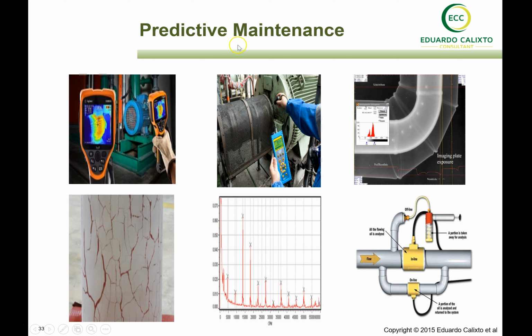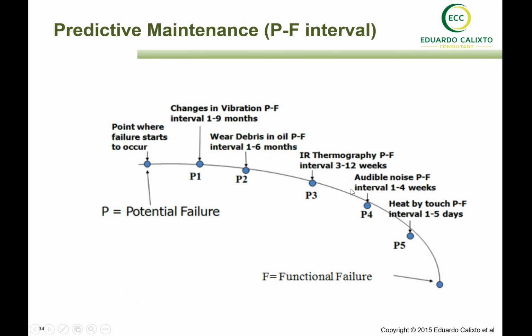So actually we have different types of predictive maintenance. We can apply for this case radiographic methods or ultrasound methods to detect the degradation of corrosion. And in this case, we are able to use the information here to predict the probability of degradation in time and predict the time that will trigger the events, and of course propose some preventive actions before to avoid that.